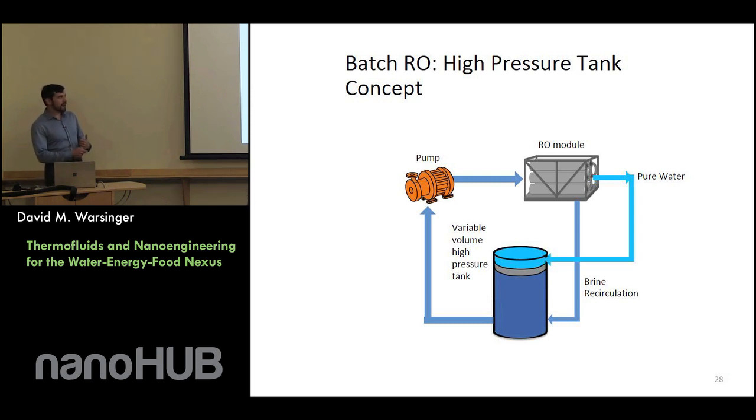So we take our main high pressure pump and we move it to fill the void space of this tank with the permeate, and then we add a little circulation pump and run a cycle like this. So this pure water is displacing this piston, and this actually is very efficient in a few non-intuitive ways. So here we have a closed system instead of an open system.